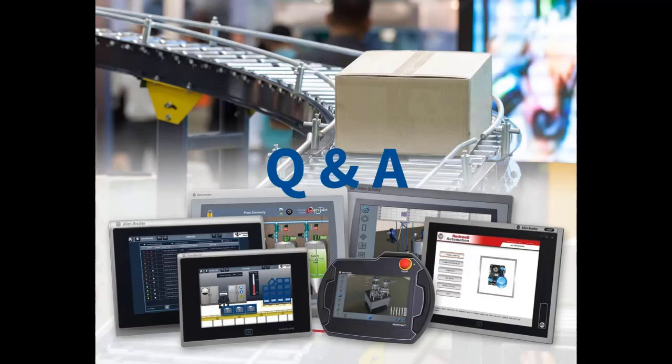And one more for you, Dan. Do the 6300s come preloaded so it's ready to run the PanelView file? Nope. There is no pre-installed Rockwell Automation software on these. Depending on your application need, you'd either install ME Station, or if you needed a little bit more power, you could install SE Station on the terminal itself. But that would all have to be additional steps, purchased and installed separately.